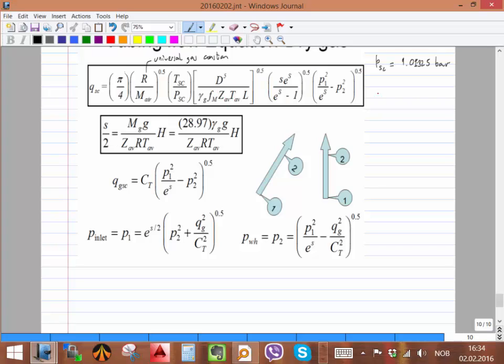Z is the deviation factor, and that is an average, and it's a bit tricky to know, because in the tubing we usually have a very high pressure at the bottom hole and a very low pressure at the top, let's say 4 bar, and this value here might be 150 or 180 bar. So there is a big change in pressure and also in temperature. So with this approach you have to find the right average. Or, like you saw in the course of Professor Golan, another option is to discretize. You go by sections. You say, for example, I want to make 100 sections, and I assume the temperature is more or less constant in each section, and then I apply the equation one by one. And this S is an elevation factor, whose expression is given here.